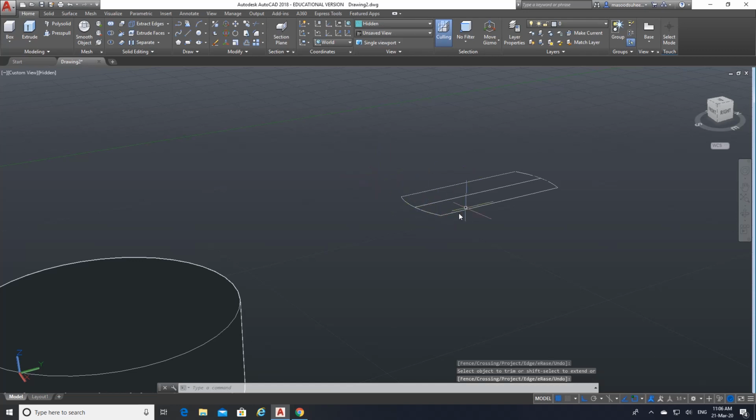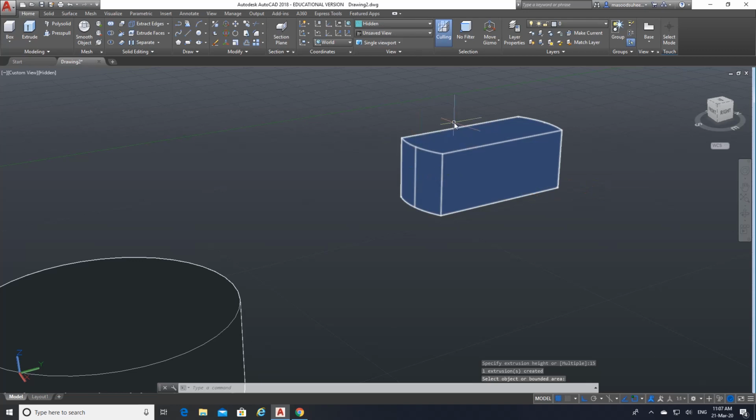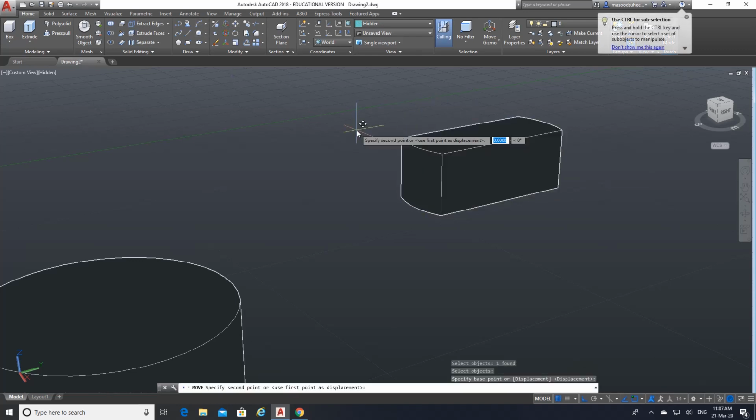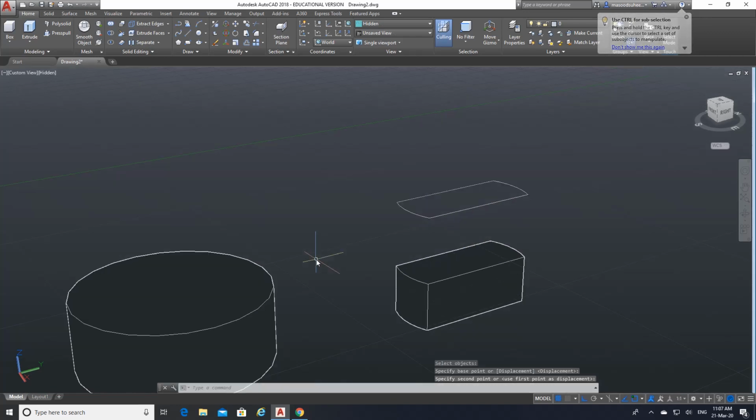Now see what you have got. You have got a very nice picture over here. The center line also I don't need, just delete it. Enter. Now let me extrude this portion. Press pull. See, everything is good. Go up. How much? 50. Enter. Enter. Okay. Now I have got the whole stuff. Let me move it out, because in the bottom I have got my template. I don't need the template. Afterwards I will delete it.